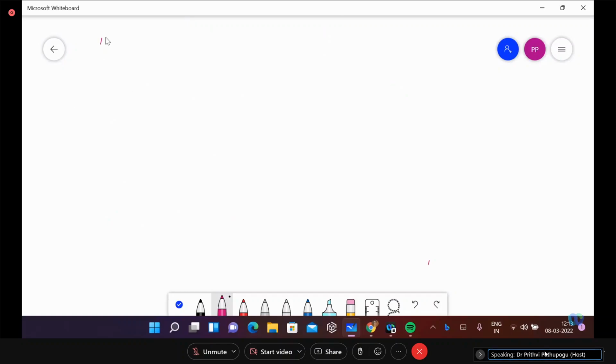Okay, so for a self test, for a RAM in specific, what are the elements that a RAM can have? Writing the data is possible, and reading the data is also possible. So read and write data will be possible. For reading or writing, we need the address location, where to write or where to read from.